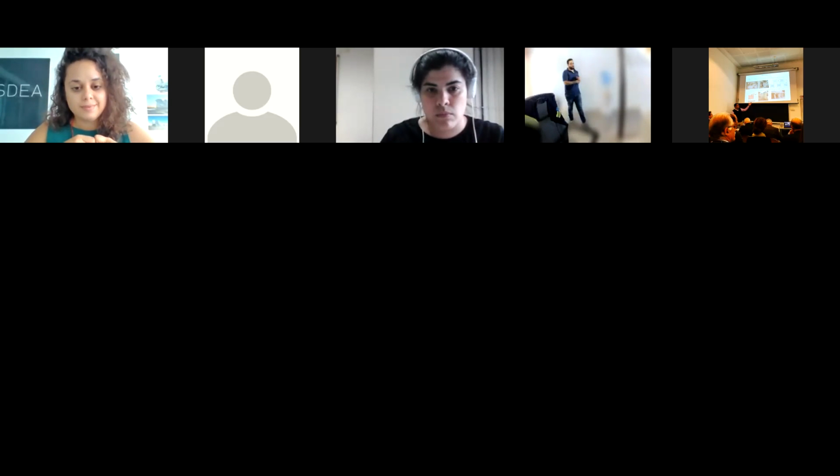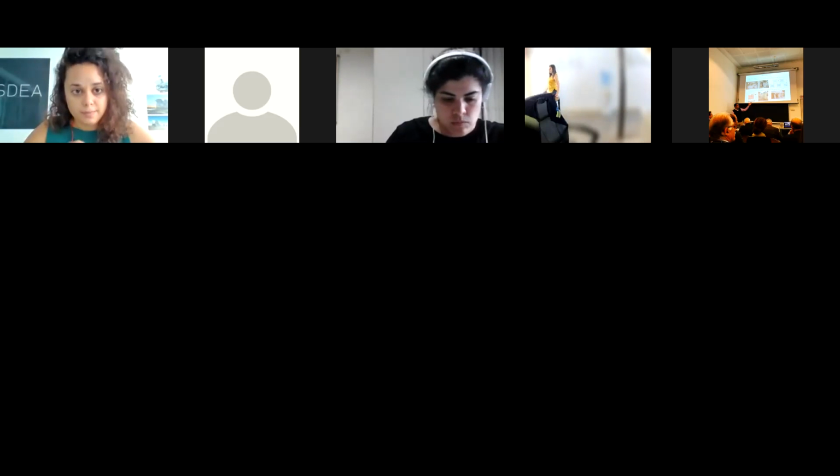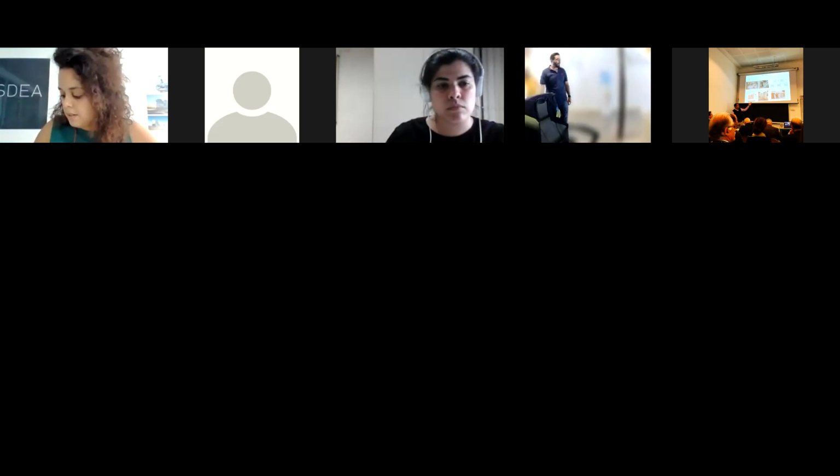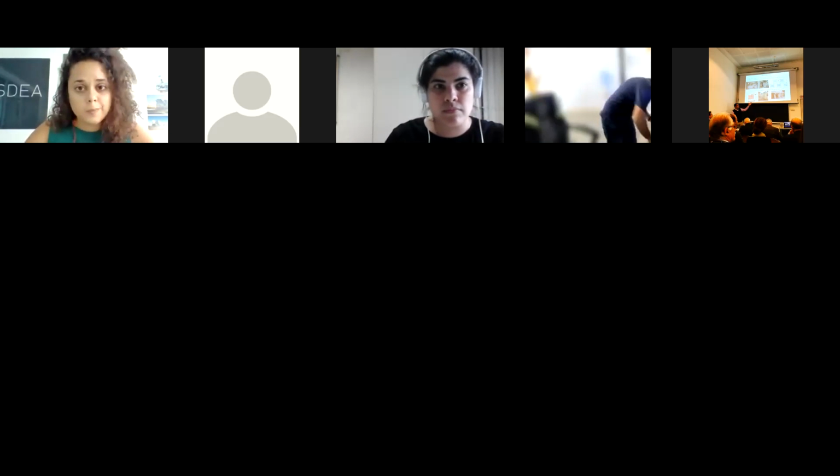Yes, thank you very much. In short, can we source one single ground motion in STKO? Yeah, you can do it through the custom command, in the analysis step. But you will need to define your load pattern also in the custom command. Is that clear? Yes, thank you very much. Okay, good.